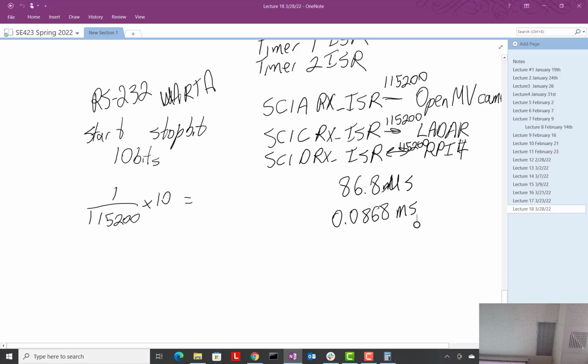If we did that one time that it took 50 microseconds for it to run, okay, these interrupts, it's highly likely that some of these interrupts would be skipped because they're running at every 86 microseconds. Okay? Or it'd be close. We'd be running in possible trouble somewhere. So then you go, oh, Dan wants me to implement the obstacle detection with the LiDAR.